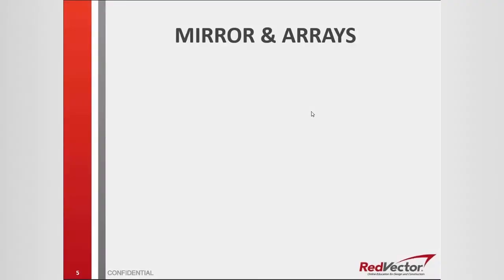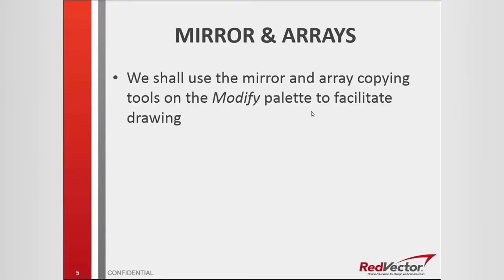We shall begin our discussion on the mirror manipulation and the array object. We shall use the mirror and array manipulation tools that can be found on the Modify palette of the Home ribbon to facilitate our drawing. We shall draw a flywheel.